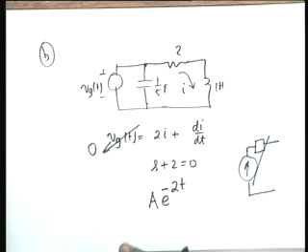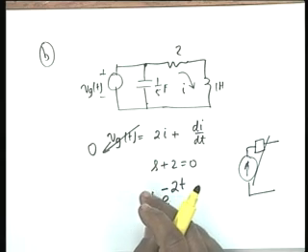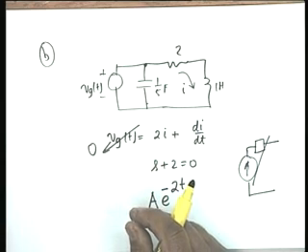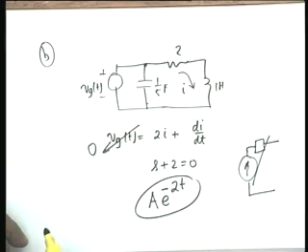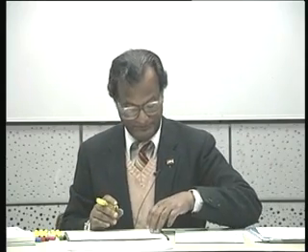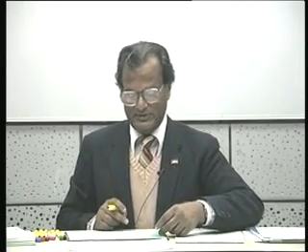You see that when it is a voltage source, the circuit is first order. When it is a current source, the circuit is second order. When it is a voltage source, it is a simple exponential. When it is a current source, it is an exponential multiplied by a sine, and therefore it is a decaying sinusoid. They are quite different. The free response of a circuit depends very crucially on the generator, and this is the point that was brought out by this particular example.